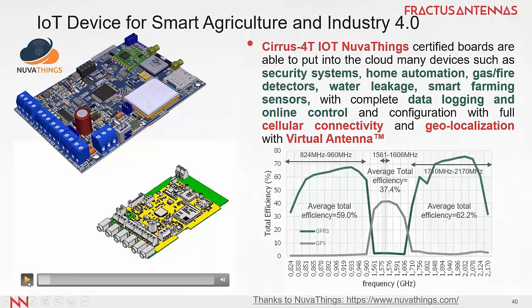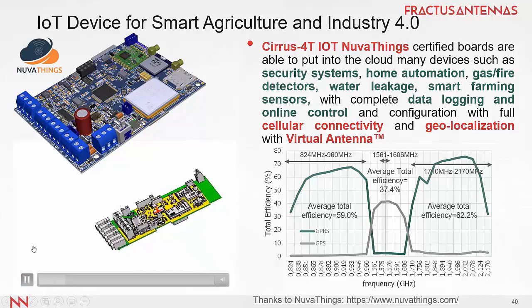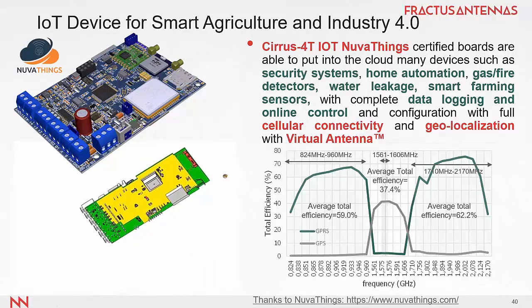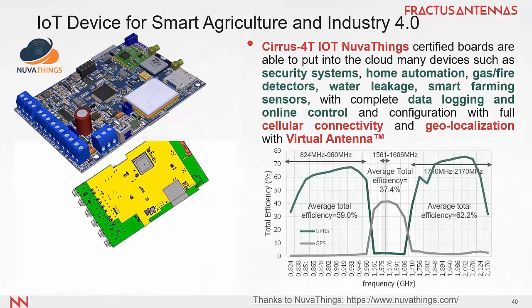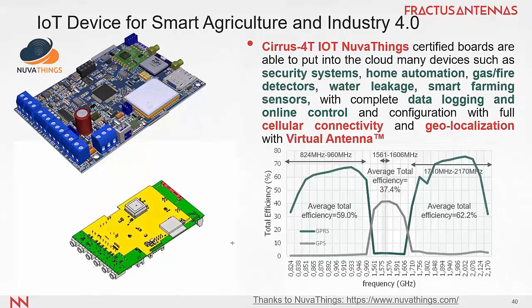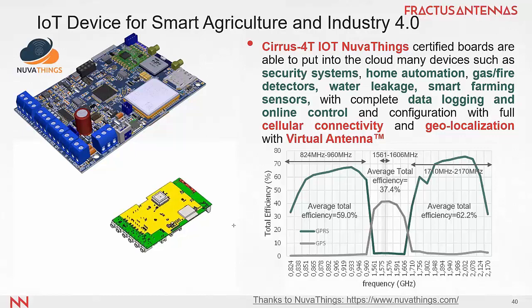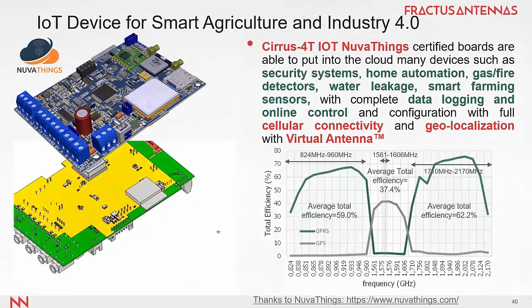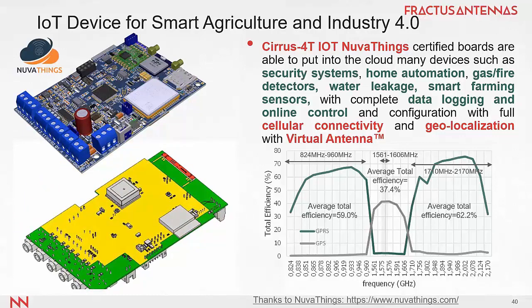So this is a nice example of how simulation helps a lot. Step number 1: optimize the platform, choose the antenna booster and put the antenna booster in its location. Step number 2: design the matching network with CST. We obtain this parameter and then we design the matching network. We can get help from the matching software, and if not, we can design our matching network. And step number 3 is to bring that matching network into the real product and measure the S11 and efficiency, and without any intervention that works and we can bring it to production.